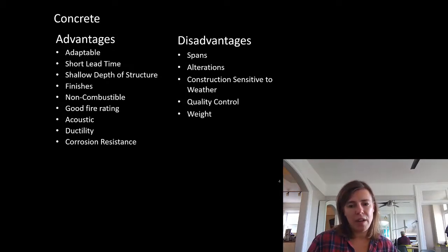So you have to be pretty good at making the mix, but water is a part of the mix, and not a lot of water. People think there's a lot of water in it, but it's not a high percentage. That means a really humid day can make a difference. Really dry days can make a difference. It can't cure, probably, don't say dry. Concrete cures. It doesn't cure well when it's really cold. So in cold weather, concrete construction pretty much grinds to a halt.